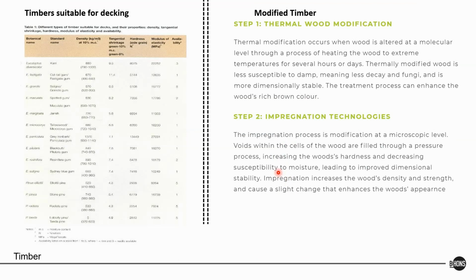When we start talking about decking, decking is a bit more difficult and it's quite expensive, so one has to be careful of that. The first thing to remember is that the typical saligna or pine timber that we often use in houses, often in interior spaces, isn't as great to use as outdoor decking. It gets damaged by the sun and dry conditions quite easily, and that has to be treated often. So every few years you have to sand it off and reseal it, and whenever you cut it, those exposed sections will have to be sealed again as well. That's the thing about timber; you have to seal it completely.